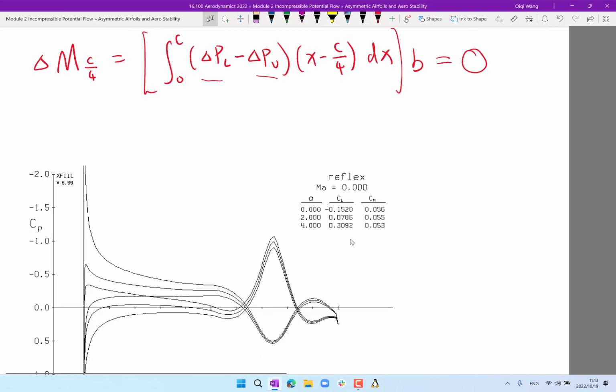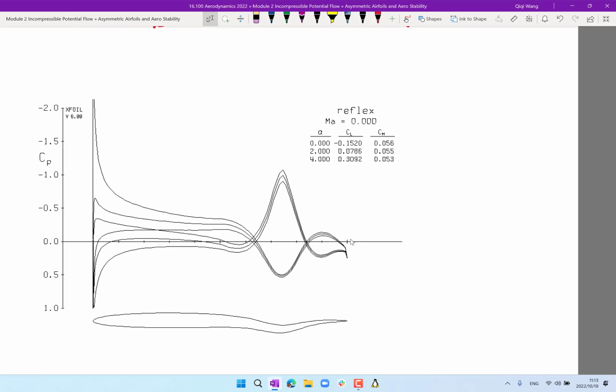For example, at the leading edge, you don't expect thin airfoil theory to hold because the assumption is not really true, right? Thin airfoil theory always assumes the flow at the surface of the airfoil is primarily in the x direction. The y direction velocity is much, much smaller. That's not going to be true over here. It's not even really true over here, right? So there is a little bit of change in the CM, but it is really, really small, especially compared to the change in CL.